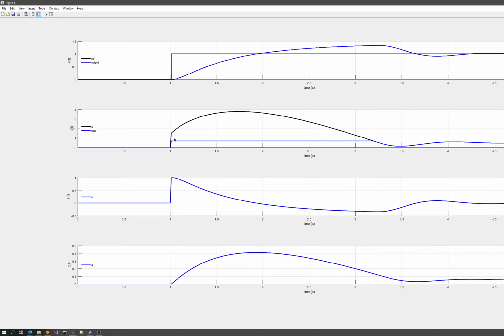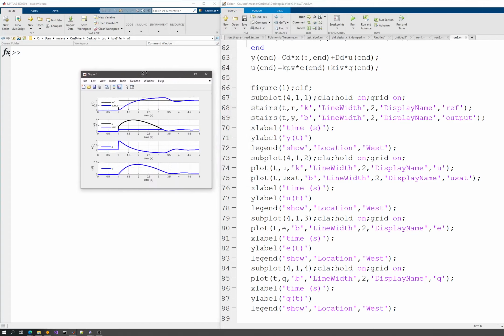So what the problem is basically is that if I have an integral, at this point my error decreases, but my integral still increases, even though my error decreases. So it's basically not the same data here, because the integral of this should not look like this. So it's not the right error. So the integrator is not aware of the saturation, because it takes the integral of this area here. It takes this into account, because you can see that it increases at a certain point, and since the error becomes negative, the integral becomes lower. But it's not due to this control signal, but this error. So basically, there's a problem, and this windup causes some problem.